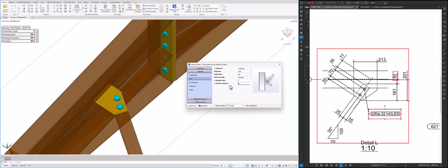You want to set it at 1, so that's to keep it at 1 like that. Then we go to bolting distance. All right, so the bolting distance, these are the bolting distances. So first diagonal distance to bolt, that's number 1. So that's from the edge of the bracing or the angle iron to the first centers of the bolts.